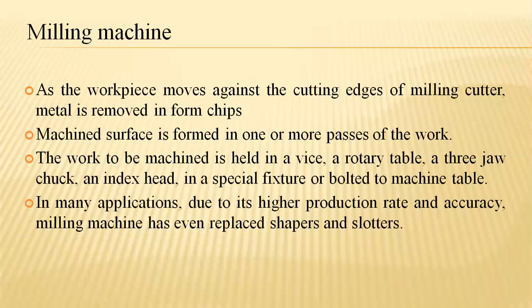For getting a particular surface finishing with greater accuracy, slotters used to make hollow structures over the materials up to a particular depth, or shape the surface finishings into particular shapes such as dovetail, rectangular, square, triangular representations, V-shaped cut, U-shaped cut, wedge-shaped cuts, etc. That too with a good rate of accuracy.